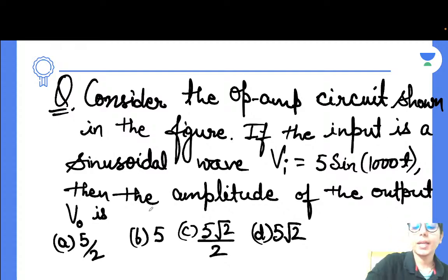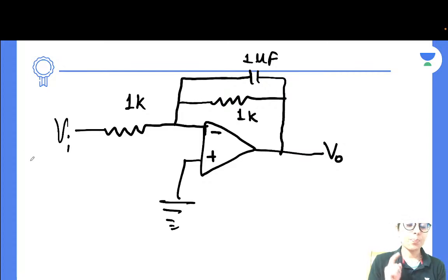Okay, guys, let me quickly explain this to you. I can't see anybody's reply or the right answer in the comments from anyone. So I'm going to talk about it. The first thing we will do is consider the gain of this expression. But whenever you consider the gain, you have to identify the circuit. In most op-amp circuits, either the input is provided on the negative input terminal or the positive input terminal or both. Otherwise, one will be grounded and the input is provided on one of the input terminals. In that case, you are going to find the gain.